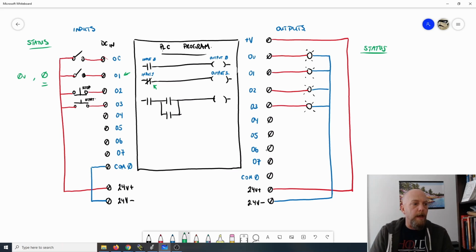Well, we definitely have the presence of a 0. So that is true. So that's what's a little bit messed up, is that you have instructions that are looking for the lack of a signal. That lack of a signal is being seen here with a 0 in the memory. Okay? This instruction is looking for the presence of a 0. We clearly have a 0 in the memory, so that is true.